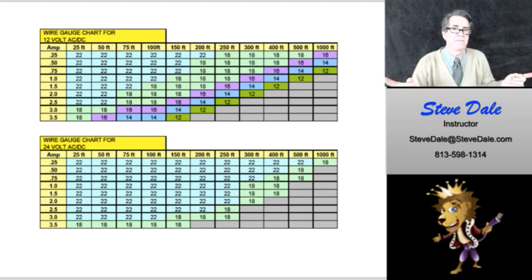They tell you the resistance per foot. So you can actually figure it out if you calculate. Well, okay, I'm going to put a bell back here. What size conductor do I need? Because I'm running 150 feet and I've got so much resistance per foot. I know I've got to supply 12 volts. How much current do I need? You know, for that.